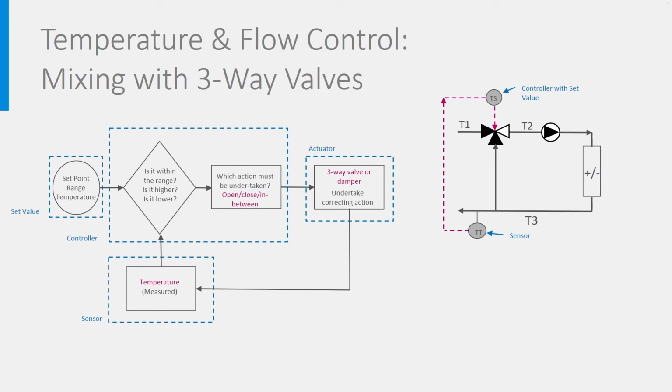In general, one wants to make sure that the temperature after this device, T3, is well controlled and remains between strict values. This is of course for the largest part done by the cooler, heater or heat exchanger, but depending on its working and the secondary flow it depends on, it may be that T3 is not always achieved.